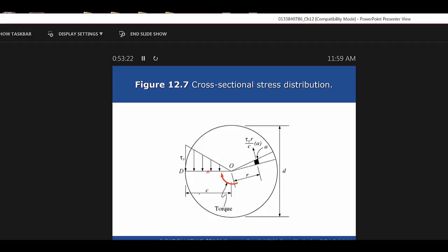Also note that if you don't know the shear stress, but you know the torque, the radius, and the polar moment of inertia, you can rearrange that calculation to get the shear stress, can't you? Well, why would that be important? Aren't you given shear ultimate, or in this case, proportional limits for shear, on the properties in the back of the book? So if we know the torque value, we have to make sure we pick the right material and maybe even the right size to be able to overcome that torque value and resist it internally. So we have to work with different things as we go along here.